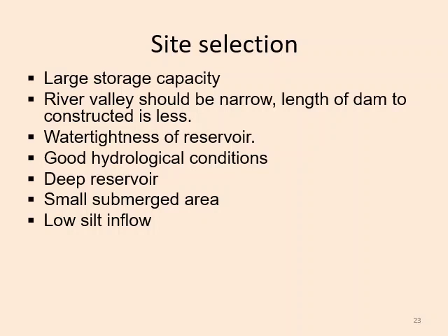From the previous slide, we know what hydrological conditions we should know first. Deep reservoir. The reservoir should be deep so that the storage capacity will be large and the width should be less, so the dam to be constructed is with less length and less concrete.